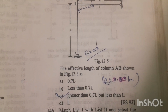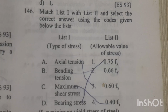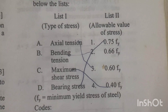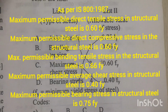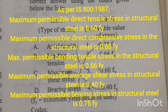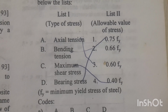The value of effective length LE will be greater than 0.7L but less than L. Question number 146. Match list 1 with list 2 and select the correct answer using the codes given below. List 1 is types of stress and list 2 is allowable value of stress. A. Axial tension, 0.60 Fy, option 3 in list 2. In list 1, bending tension, in list 2 it will be 0.68 Fy. In list 1, maximum shear stress will be equal to 0.40 Fy.